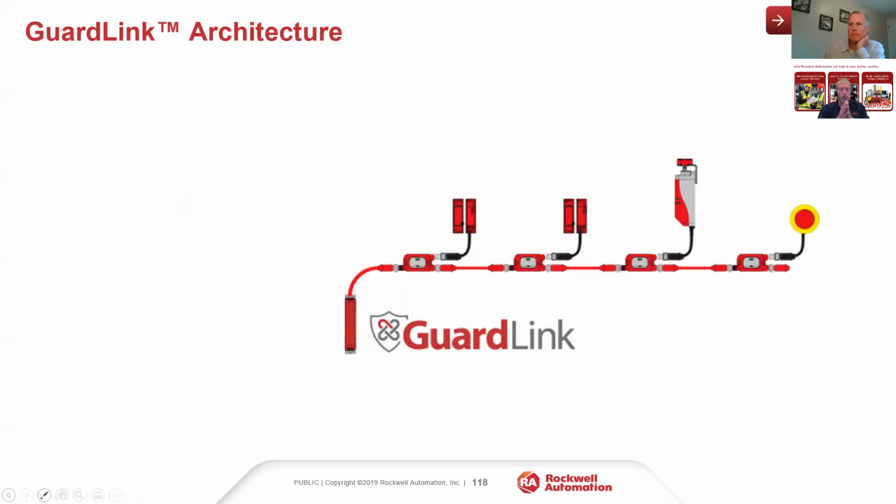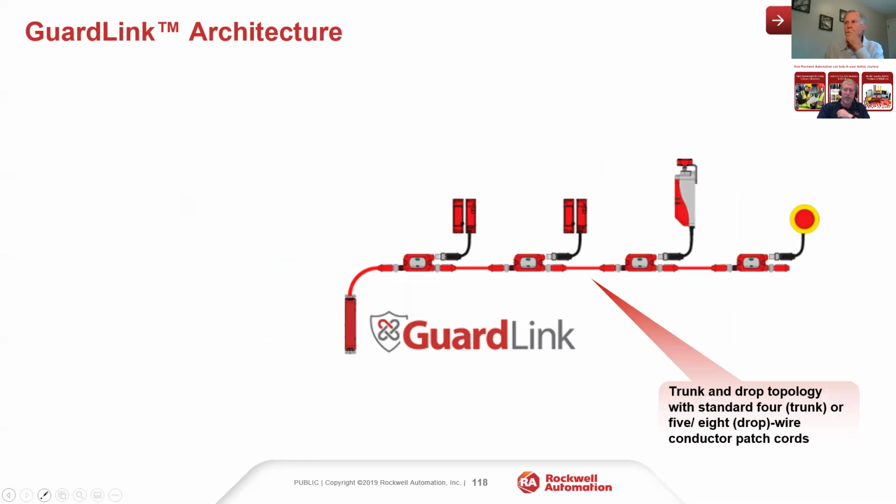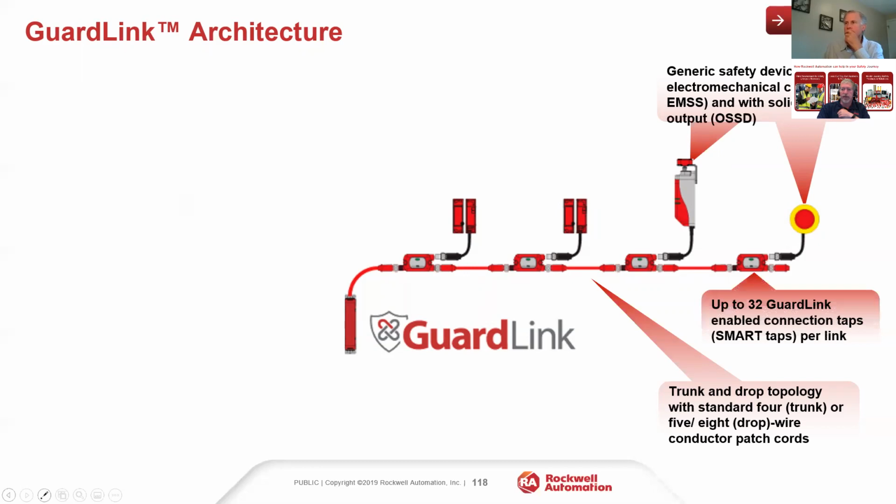So the next thing we'll talk about is the technology path that is phase one is complete, and we're continuing down the path for additional implementations. Phase one of this solution called GuardLink is through a safety relay, but GuardLink is basically a trunk and drop topology that uses standard 4-pin cables for the trunk and 5 or 8 depending on what device you have connected to. You can use whatever generic safety device you'd like that connects into these smart taps.